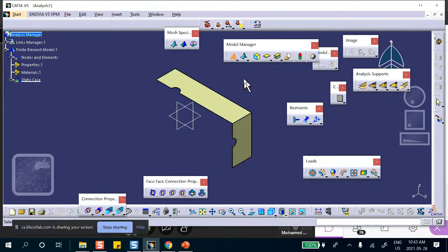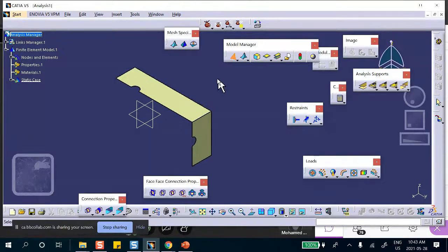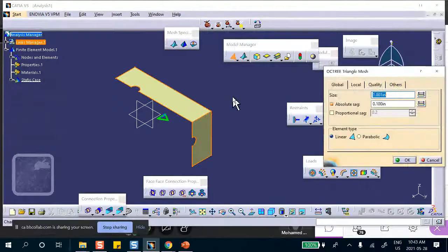Okay. So notice that when I select anything, the top or the bottom, it takes the whole thing, even without a join, because of the fact that this is an extrusion, okay? But if you do it the book way, and if you don't join, the top is going to be meshed separately, the bottom is going to be meshed separately, and because of that seam, there are multiple node numbers here, and there's a problem, etc., etc., okay?